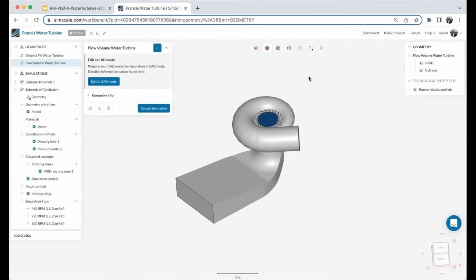Now, since this is a CFD simulation, of course, we want to be simulating the flow in the negative space, where that water flow domain actually encompasses. So in this case, we want to make sure we create that flow domain. We can create that externally in a CAD program, or we can create it in our CAD mode if you have that solid body assembly. And it's really just a simple 3-click operation to generate that flow domain.